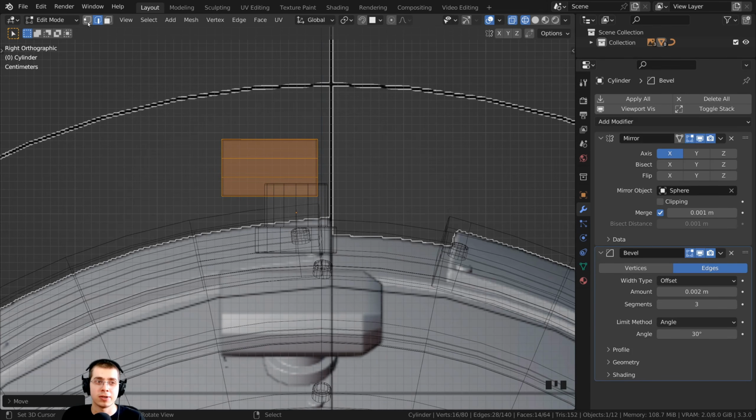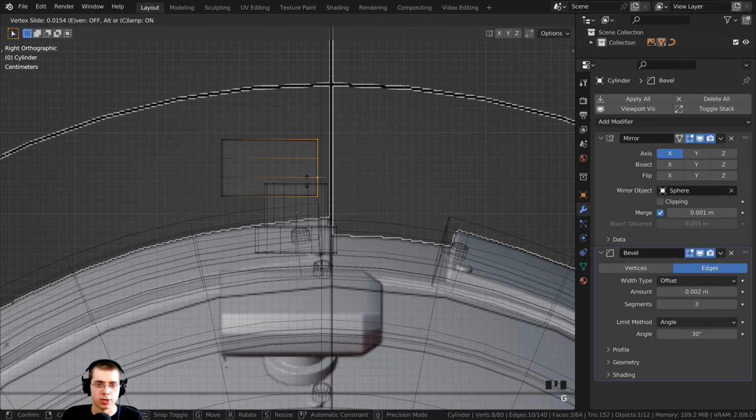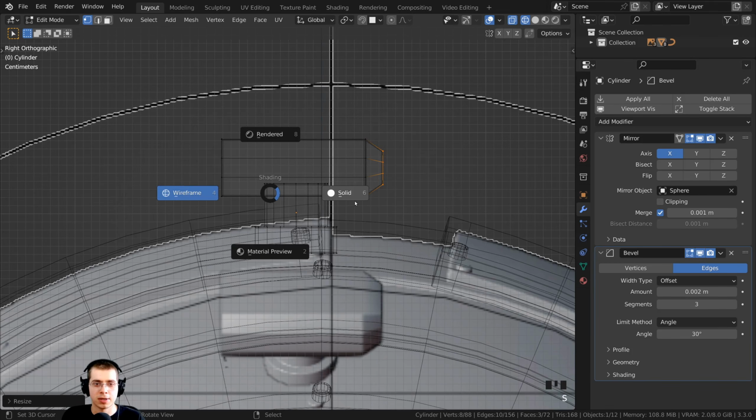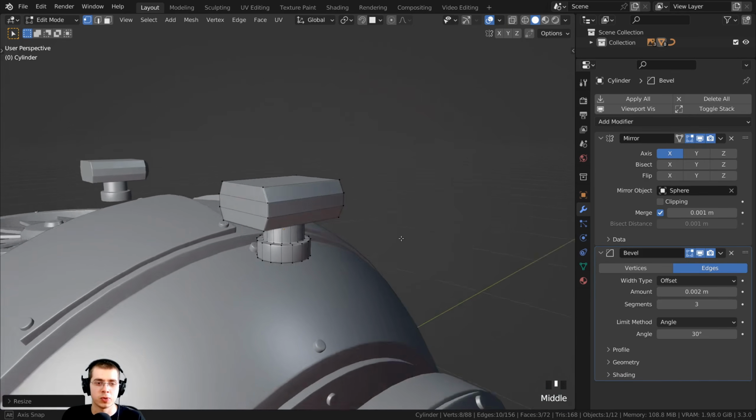And then I want to click right here to go to the Vertex Select, and I just want to deselect the front so I can bring the back. So I'm going to press B for the box select, and then I'm going to click and drag with the middle mouse wheel and drag over the front and then let go. That's going to deselect it, and I can press G to grab. I'm going to click with my mouse wheel to constrain it to the y-axis and stick it there. Then I can press E to extrude. We're going to extrude that back and hit S to scale and scale that in. Hold down the Z button, go back to solid view, and we now have a pretty cool object there for the headlights.